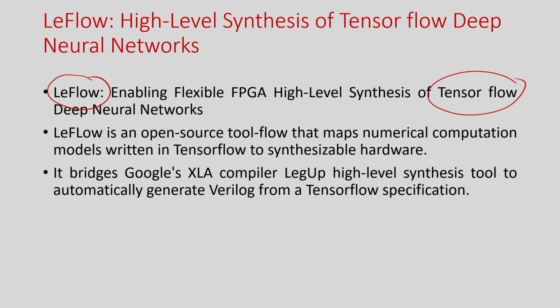What LeFlow does is very interesting. It does not develop any new high level synthesis tool; it just uses the existing high level synthesis tool called LegUp. What it does is take the TensorFlow code, use the Google XLA compiler, and convert that TensorFlow code into LLVM IR, some intermediate representation which the high level synthesis tool can understand. If you look at a high level synthesis tool, it basically has a C compiler at the start.